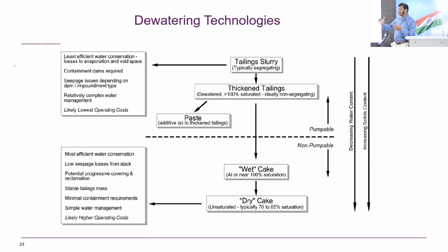So if we see in our piezometers that we are becoming nearer to the threshold value, then we take some steps. We identify those areas. The first step is to stop further loading, because the pore pressure will keep increasing while you are loading. The first thing is stop loading, stop operations. The second thing is to dewater it. I am not saying much on the dewatering, but I will give you one example.